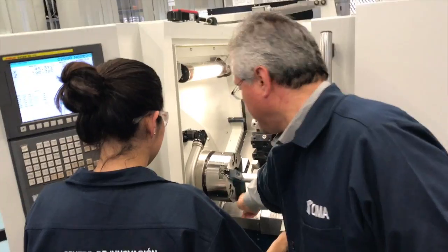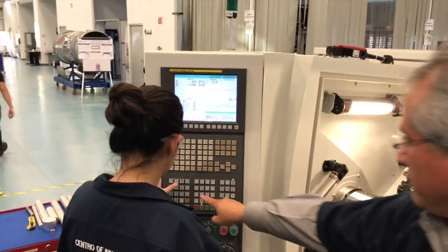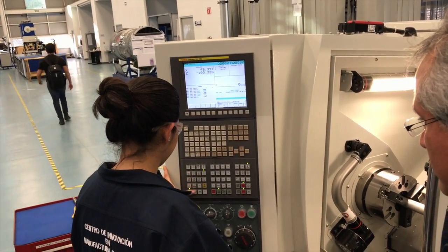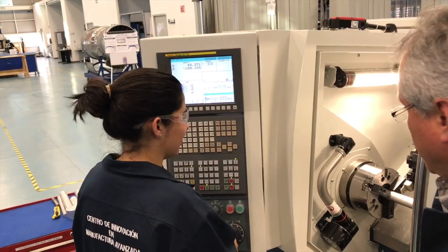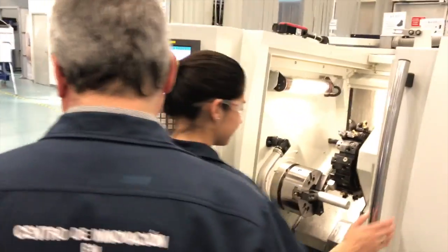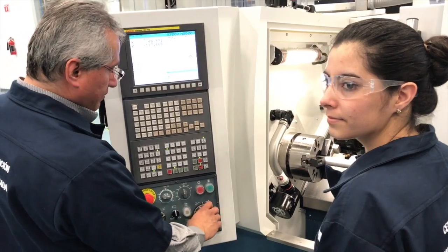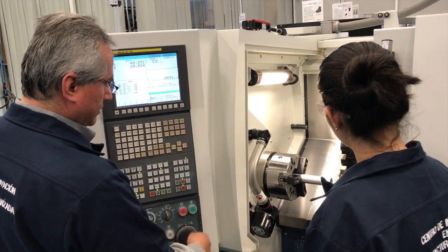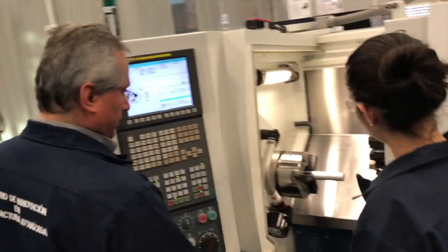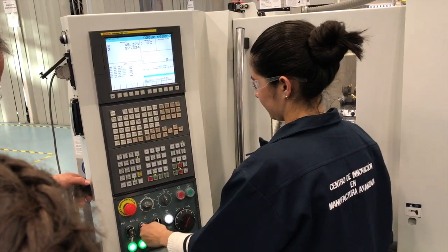The next step is to use MPG with an adjust feed rate to move the tool turret using X and Z soft keys. This procedure will help us to verify the turret tool will not collapse with the chuck. In our case, the turret will move up to minus 117 mm in the Z axis. This is 11 mm more than the required length for our final part. Finally, the door must be closed to start the next procedure.